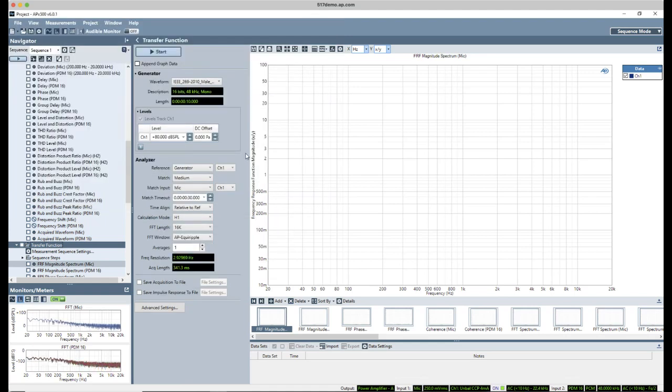Now, the next little bit that I do have to admit is that one thing that is confusing is the signal generators in AP software are calibrated according to the peak level of a sine wave. If you're generating a different kind of signal, in this case a speech signal out of an APX, and it has a different crest factor, you really have to add that crest factor to the signal level in order to get what you might expect.